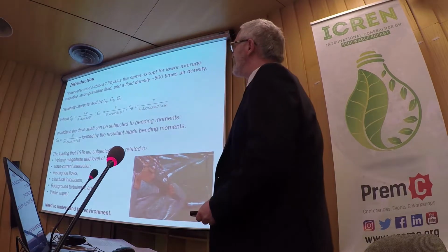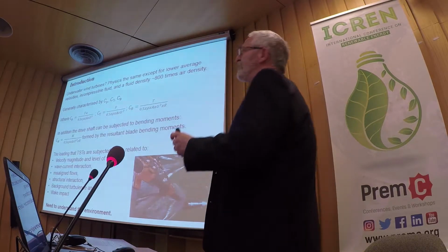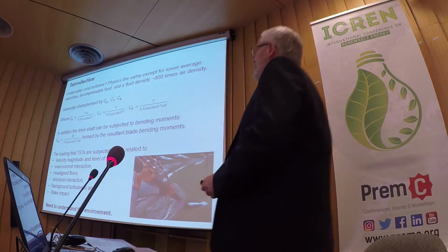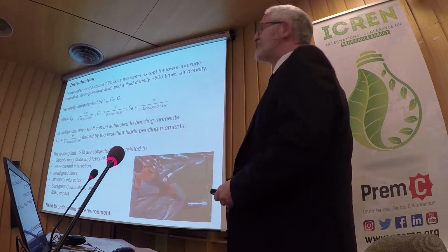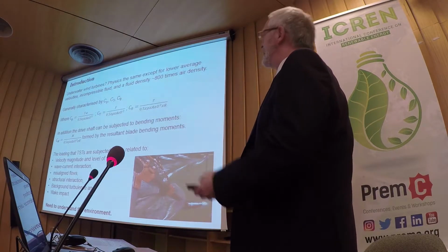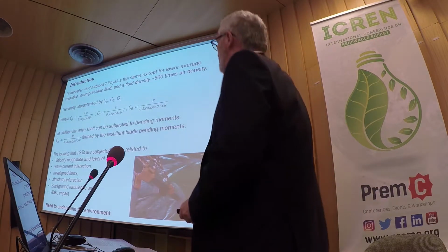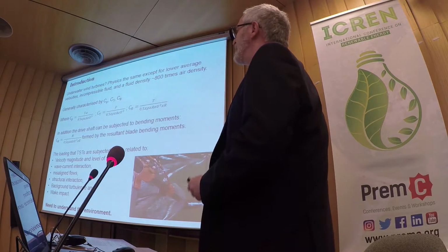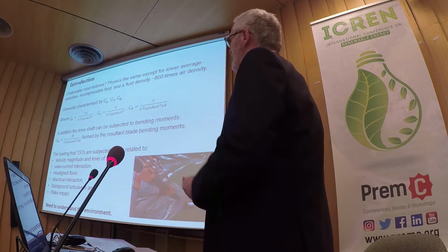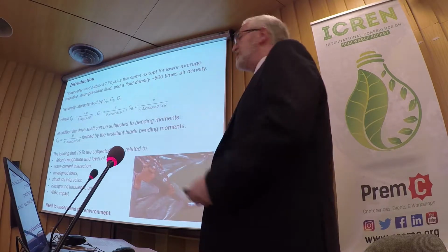The power coefficient, the torque times the angular velocity over the available energy in the swept area of the turbine. The thrust is just the force that's acting on the body, and then the torque, obviously the alternative force component. In addition to that, what we're also looking at is the moment coefficient, which is a result of any bending or asymmetry that's occurring within the turbine blades.